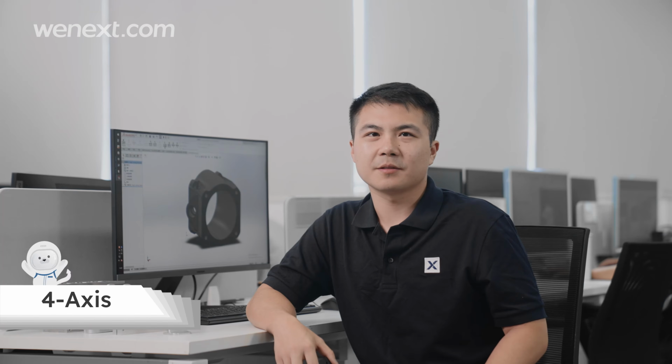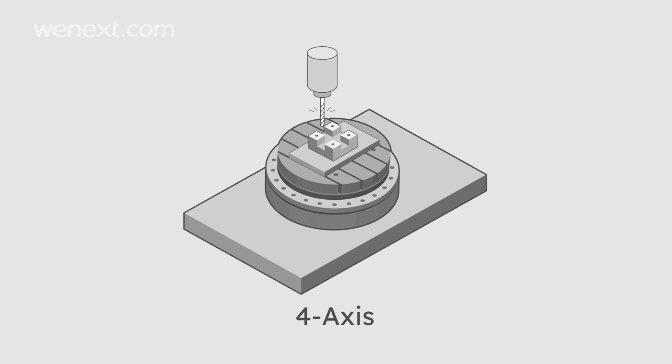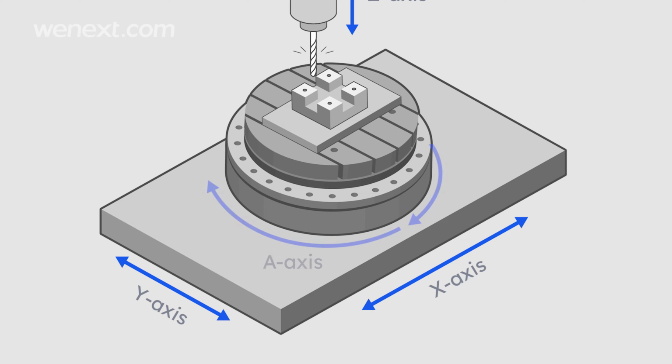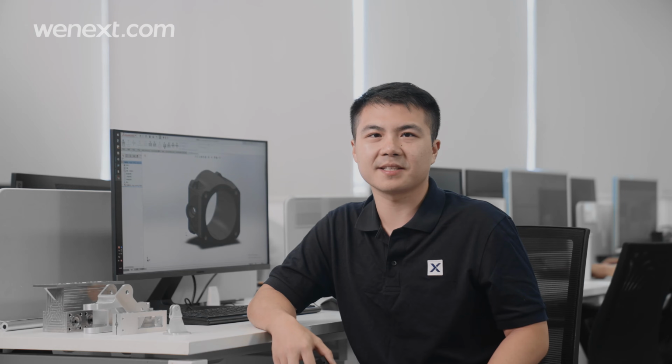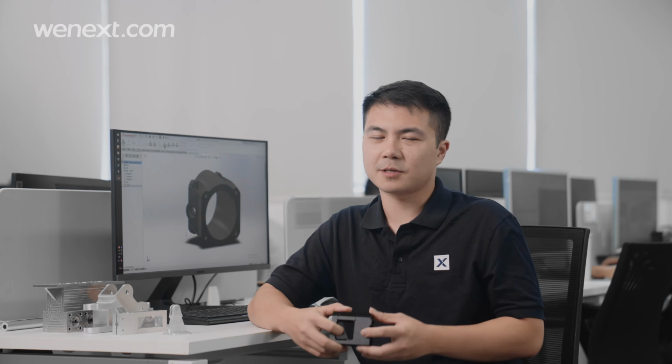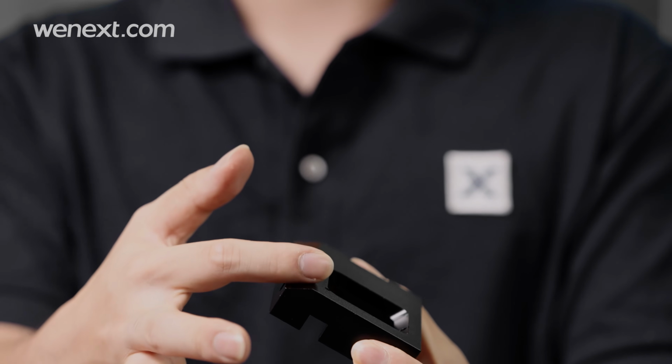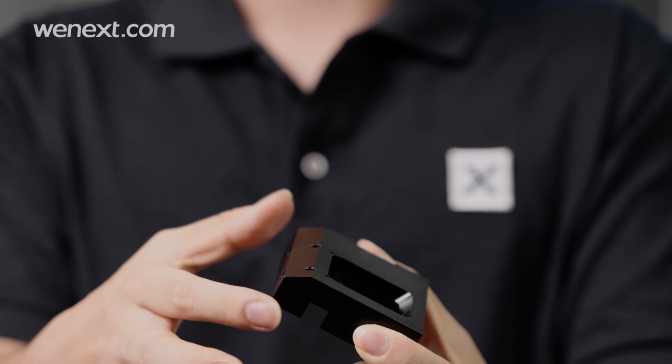Speaking of 4-axis, we generally understand this technique as 3+1 axis. In 4-axis, the machine also has X, Y, and Z, and adds an A axis that rotates around X, so we call it 3+1 or 3+A. 4-axis comes in a few different arrangements, but generally they are vertical machining, which means the spindle rotates around Z. Normally, a block of material is mounted on the X and rotates on the A. Therefore, 2 sides of the part can be machined in a single fixture setup.